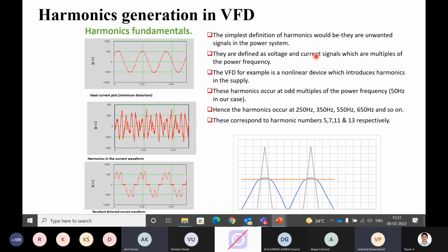And if you take here in Tamil Nadu, the local EB is also putting some standards. The THD should be less than 8%. Otherwise, if more than 8, they will put a penalty. So the local EB people will come and measure that harmonic level in your premises. If it is above 8%, they will put a penalty. So it is very, very important to keep our entire building under control because of harmonics, because we need to see and study the harmonics.